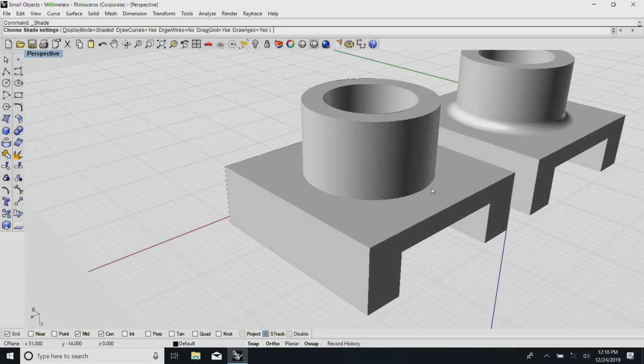This one has been done by milling. In the case of milling, there still will be a small, what do you call, fillet, which I will try to show you, because it is not easy to get into this. The milling part of it is on the groove on top side, the bottom one is by turning it. What they have done is, in fact, done in reverse.